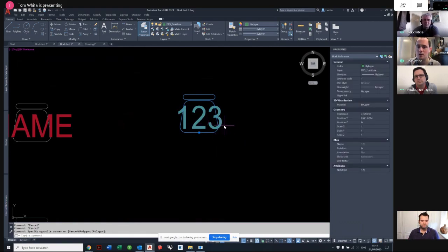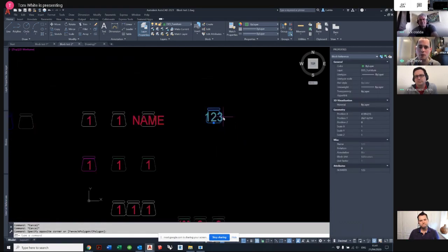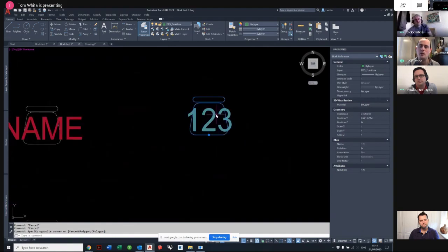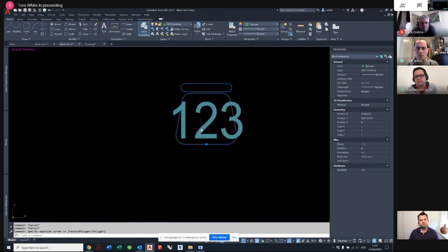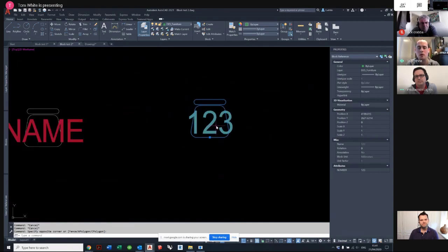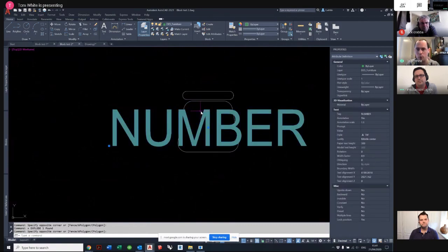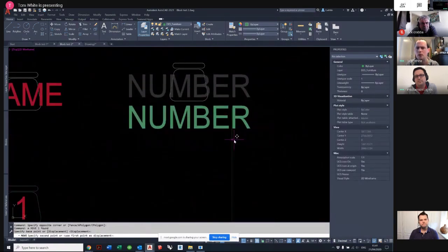Yeah. Dick, can I just describe one other thing which might or might not be helpful in your circumstance? If I'm doing power symbols, for example, you might put a phase and then an amp, and you might desire for them to be on two separate lines. I don't know, Dom, if you have a specific way of doing it, but in this circumstance I'm going to explode this, and the number, I'll make it a bit smaller.